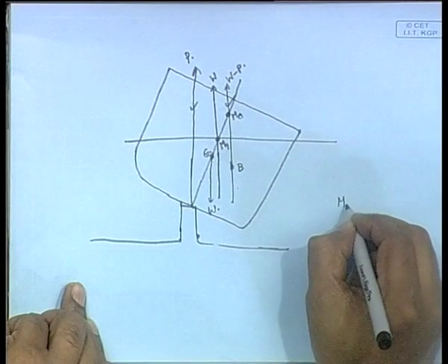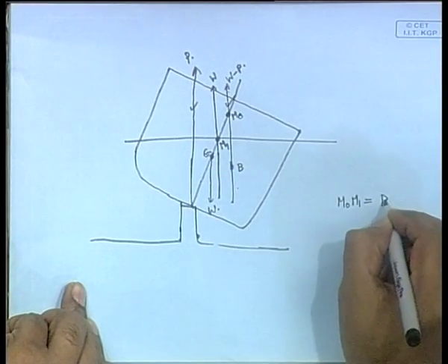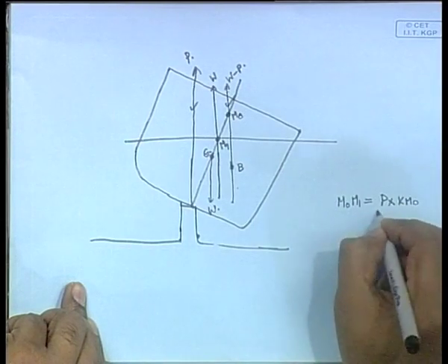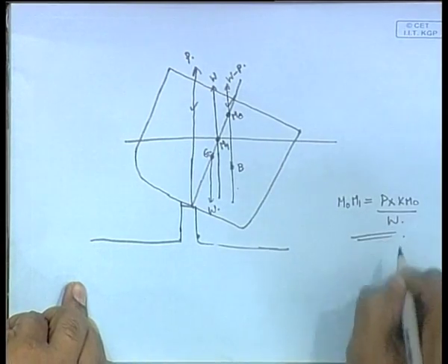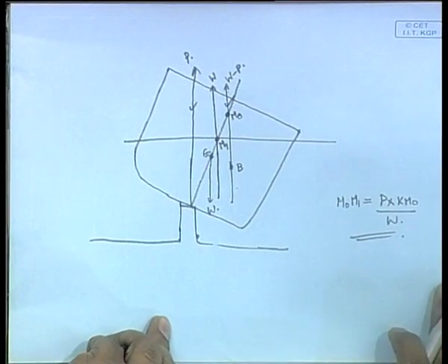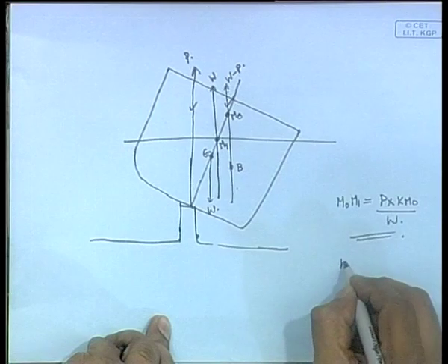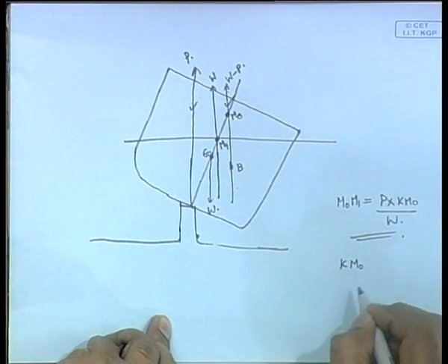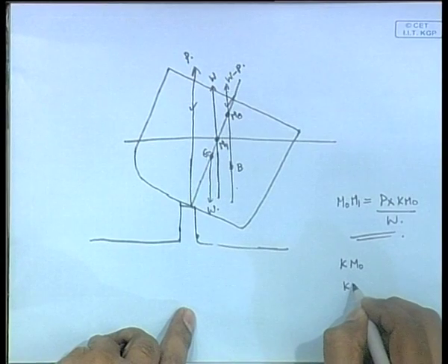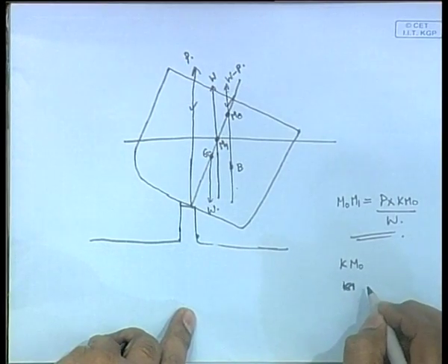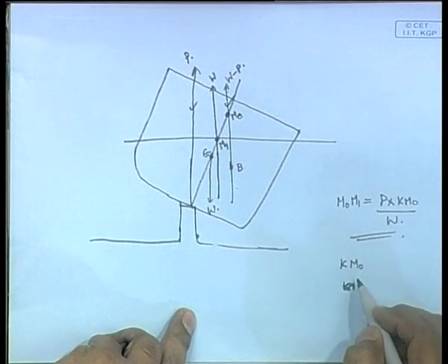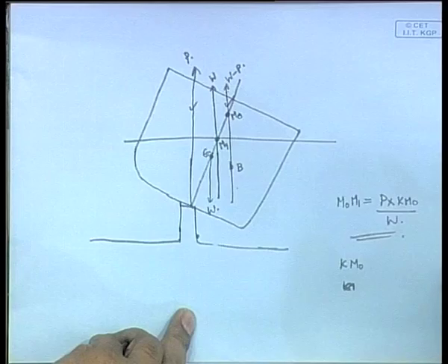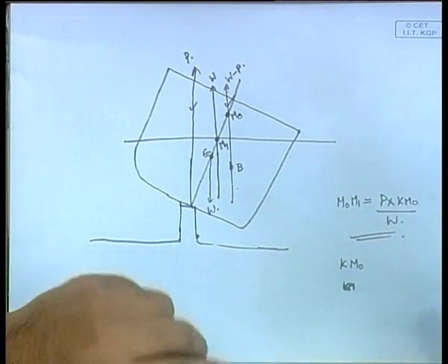This is the first part, and we got an expression for this change in M. I will not do that again. M0, M1, it became like this. This is M0, M1, this is the distance through which the metacenter shifts. Therefore, if we have our initial KM0, how do you get that? It is always got from the hydrostatic data. Hydrostatic data will always give you KM. So, KM0 means without any P, that is, once you consider the ship, there will be some KM.